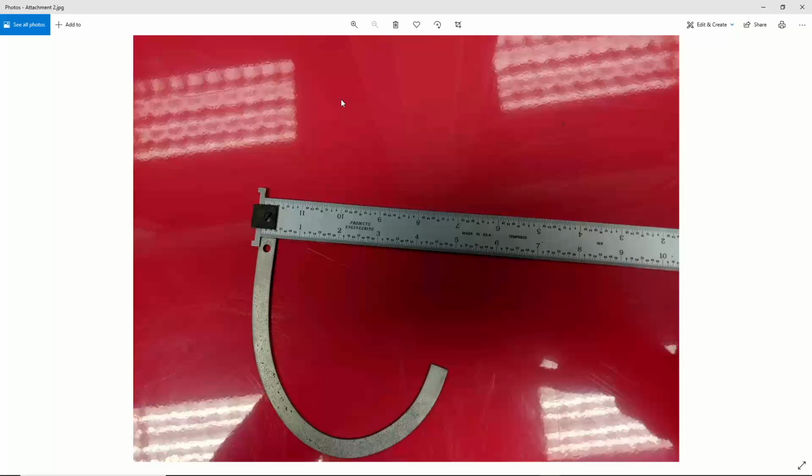And then I got a piece of, I think it was, 1/4 inch divided square graph paper. And then I just traced it with a real fine-tipped pen and plugged it in. And then we were able to use that geometry. I brought it in, I drew everything out, cleaned everything up. And then we cut a stamp. We just basically used a V-bit and had it come to a point. It was a big steel gasket punch, essentially, and the way he ended up working it out is he got it hardened. They set it on a gasket, smack it with a hammer, and that was as easy as they needed to go. It was quick and easy.